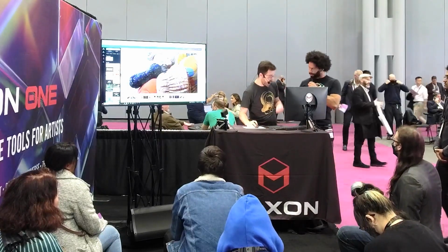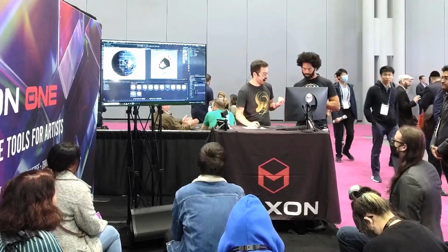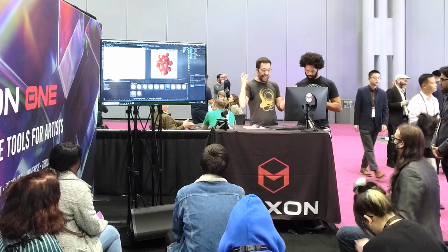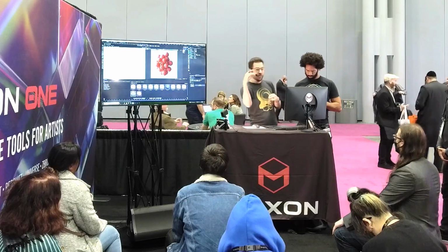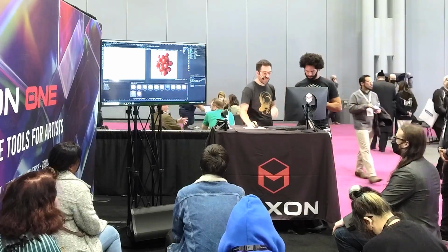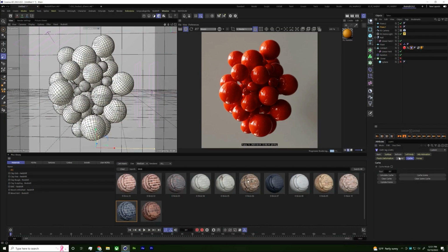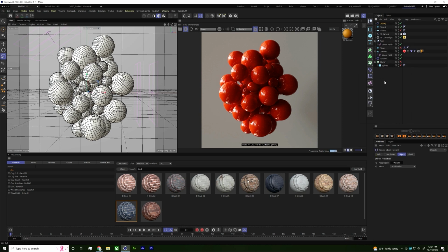Awesome question. So the question was, I changed the gravity in this scene here, my first tutorial. And can you have gravity affect things differently and not just have a global gravity? Can you say, all right, these particles go up and these particles go down? Great question. Totally doable. What you do essentially is turn off your global gravity, which is Control D, and right here in gravity, you can just zero it out. And then if we do a Shift C and type gravity, we have a separate gravity effector, essentially.